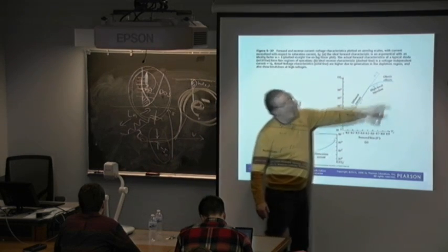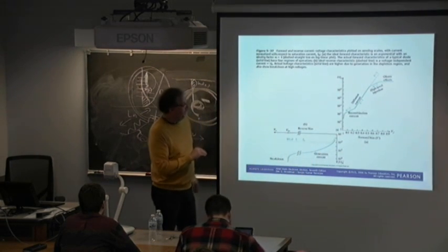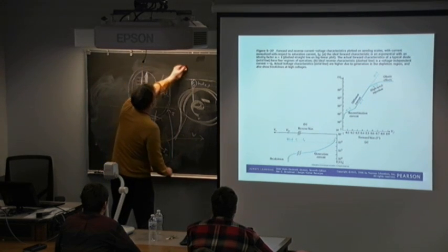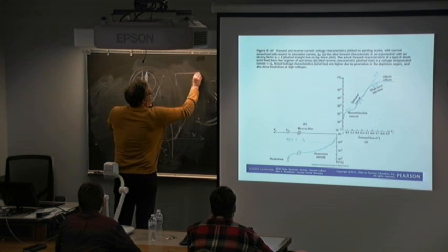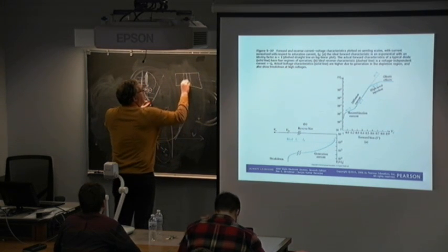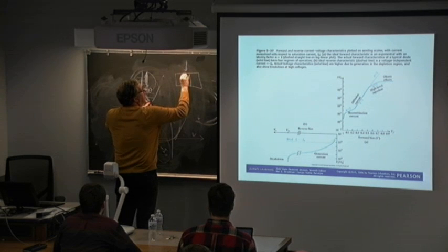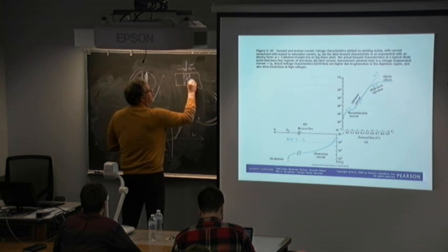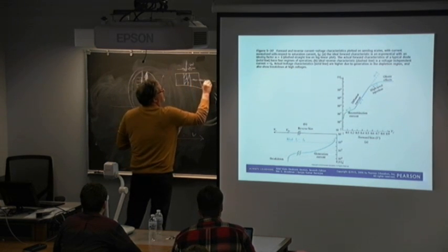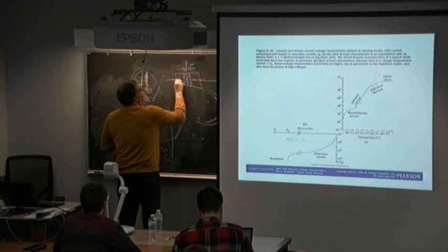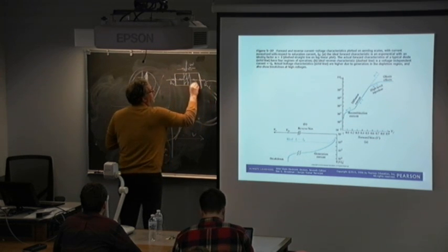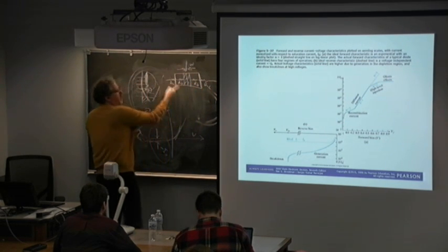And then you get the ohmic effects where it rolls over. So in the ohmic effects, what I mean is the other parts. Here we're normally worried about what happens in the depletion region, W. But now the ohmic effects means that I have a resistor there, and there, and there, and there. So this is going to be the resistance of the contact, and the bulk. So I get this lumped element.